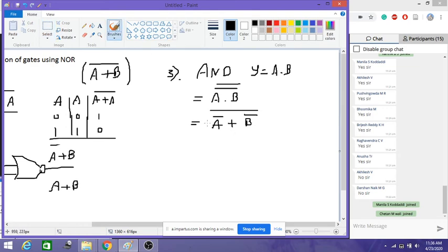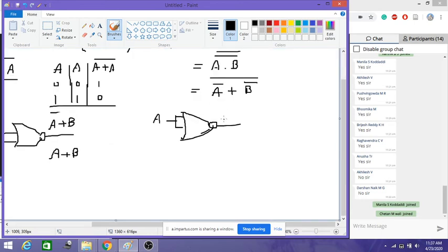Okay, so now before applying directly to get this, first we need to find the complement of A, then complement of B. So we know how to get it with the previous NOT gate example. So just pass these two inputs with the same variable. I'll get here A bar. So likewise, you get this here B, then we'll get here B bar. Now you combine this.